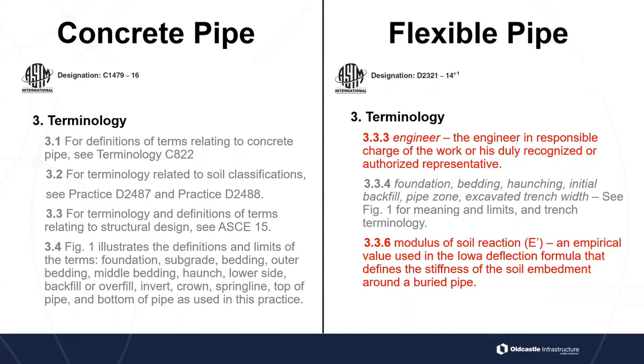So it's very important for the design engineer not only to go through and do the calculations, but to verify through inspection methods or through compaction tests or something, so that they can look and ensure that, yes, it does meet the design that they called for, and that modulus of soil reaction, that E prime number, meets the stiffness of the soil that we are providing. So is it structurally complete? Well, we hope so, but it is up to the engineer to verify that it is.